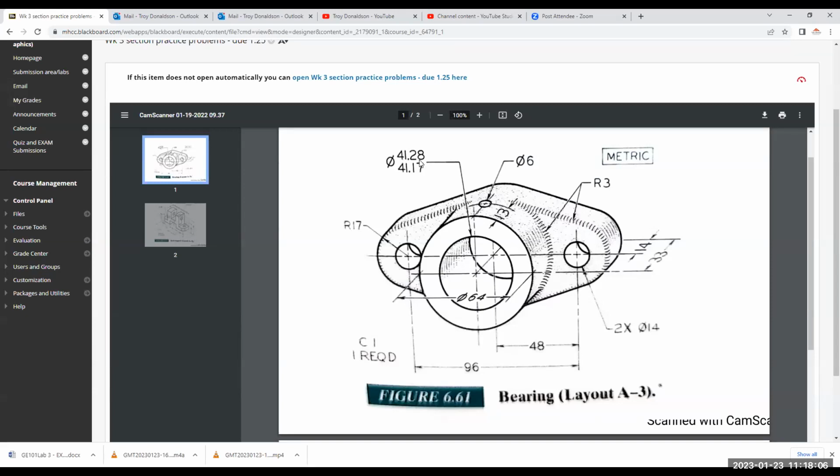If you just list one measurement and hand it to a machinist, they're going to try and nail that, and they could spend hours trying to get it that accurate. If you give them a range and it's a hole, they'll shoot for the smaller number, right? If they miss it a little, they remove too much material, it might still be within the range. Much faster process, cheaper. Money is what the difference is. Yep. So here's the deal. When you draw it though, what do you think you draw it to? Which number? Because you can't draw it to two numbers, right? For a hole, the smallest number.